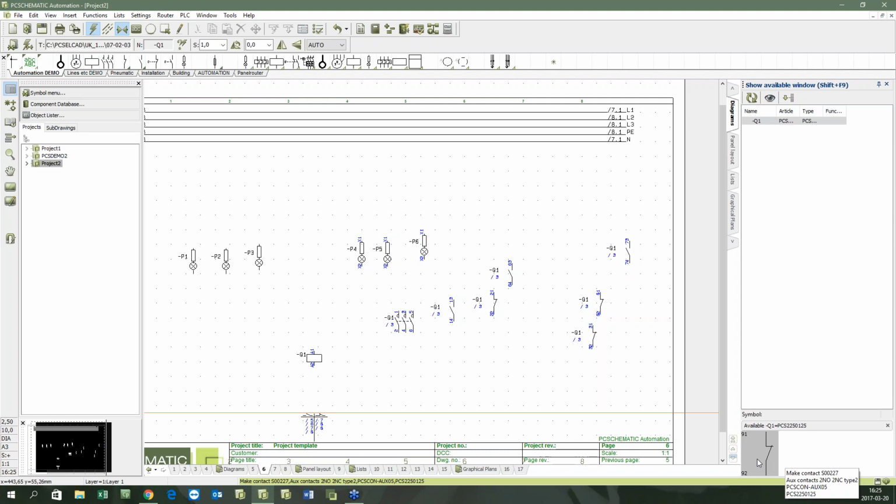So that was 3 different kinds of accessory: the fixed, that you cannot edit in the project, then you have the mechanical, which is mechanical accessories, something that you don't connect to or that you don't show in the diagrams, such as sockets, for instance. And then here I have the electrical accessory, which is components or symbols that you can attach to other components, but you show them with normal symbols. You simply give them the same name and you know that they fit together because it's been stated in the database. So that's the 3rd kind of accessory that is in here.